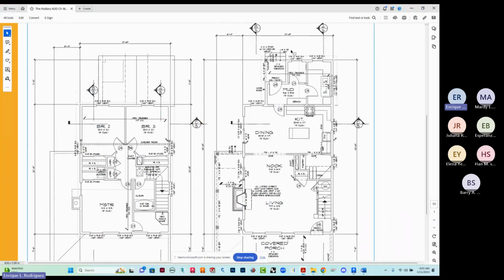Now what I got to do is I got to start cutting this portion out of it. And I don't have dimensions for that, but I do have a dimension where this location of this wall is from looking at the second floor. So if I look at the second floor right here, you can tell that that's 11 feet to the outside wall on the second floor, which happens to coincide with this wall right here. That becomes what we call a bearing wall, and that's the only interior 6-inch wall that we have.